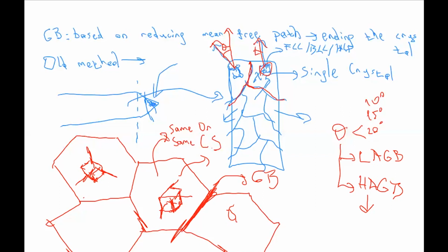And there are transition regions between the neighboring crystals, because these two are different crystals. They are each a single crystal. And there is a disturbance in the atomic packing. So the packing of this crystal is different from this crystal. And these transition regions, like the grain boundaries, can also be walls, and may consist of various kinds of dislocation arrangements.